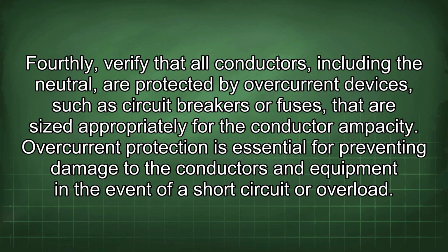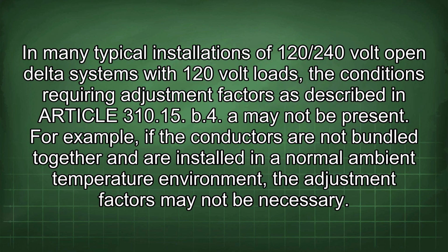Fourthly, verify that all conductors, including the neutral, are protected by overcurrent devices such as circuit breakers or fuses that are sized appropriately for the conductor ampacity. Overcurrent protection is essential for preventing damage to the conductors and equipment in the event of a short circuit or overload.